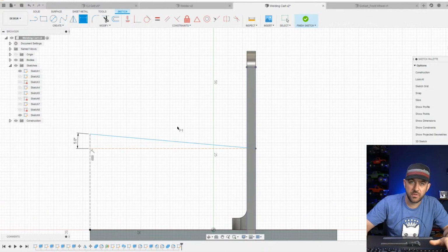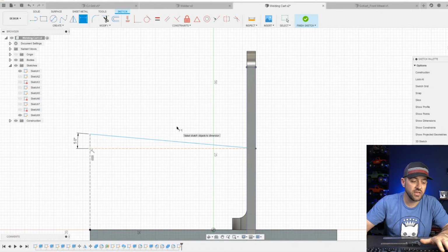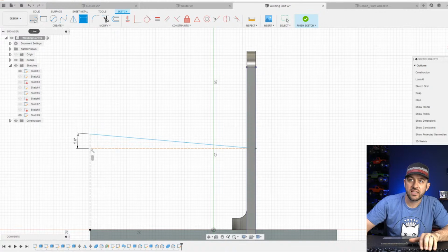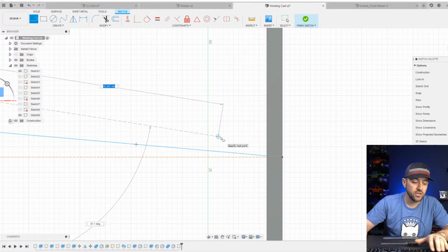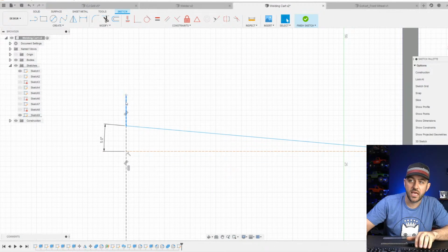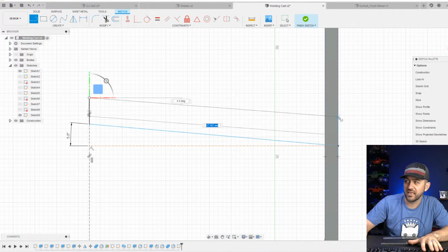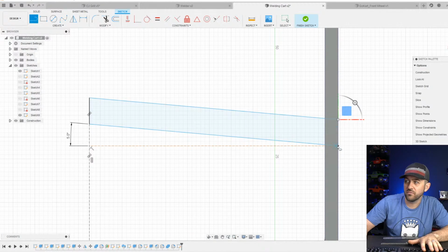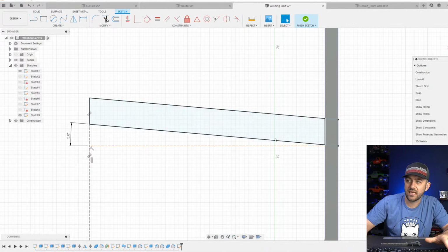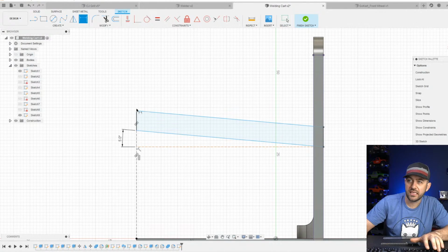So, and that's not much of an overhang. A 5-degree angle is a very tame overhang that I think any of you who have a printer are probably more than capable of doing. A lot of these things will do 30s and 40s. If you do a calibration print or a test tower, you're probably easily going past that.